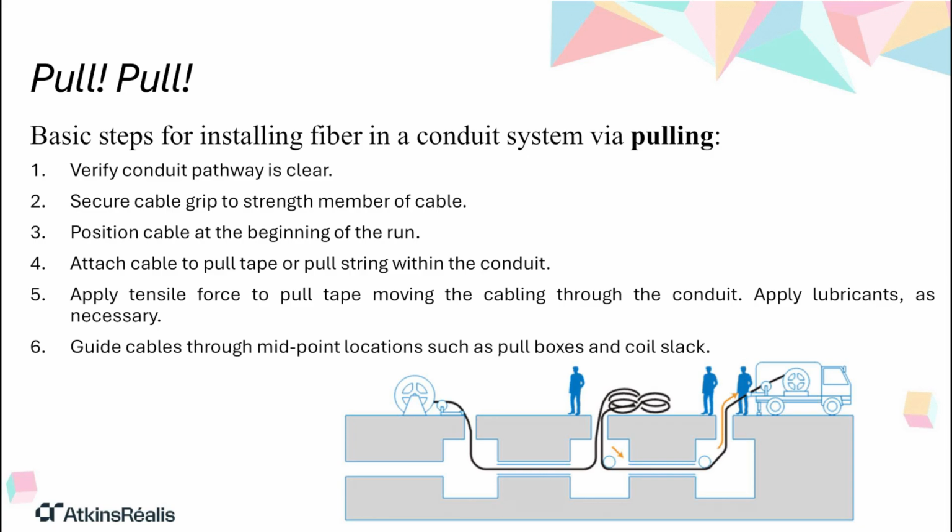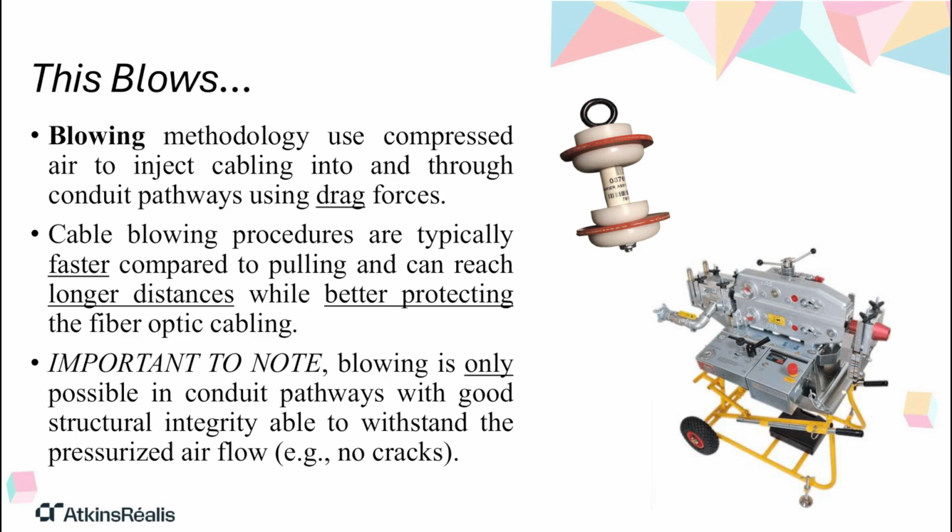It can be. And there's always a risk of exceeding the cable's maximum pulling tension or bend radius if you're not careful, which can damage the fibers. Distance is also a limitation. So what's the alternative? Blowing. Yeah, cable blowing or jetting is more advanced. It uses high-volume compressed air. You attach a small piston or carrier, sometimes called a rat or missile, to the cable end. The air pushes this carrier, which in turn pulls the cable along, while the airflow itself creates drag forces along the cable jacket, effectively floating it through the conduit.